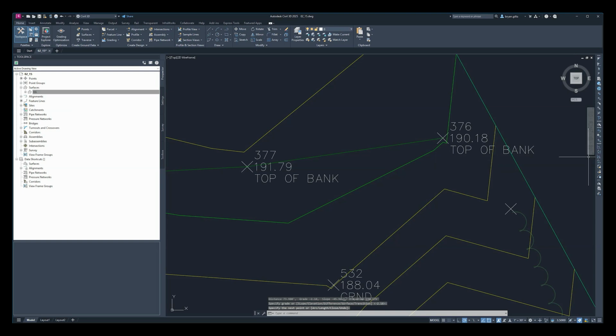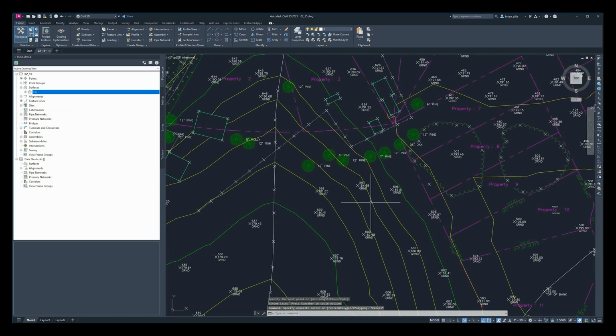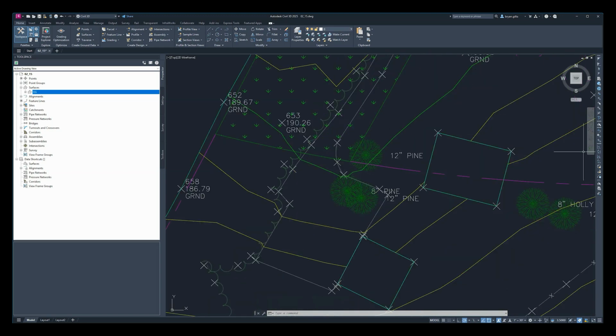So now that we have that feature line created, let's pan to the south lines of parcels named Park 1 and Property 2. So again, if we zoom all the way out, it's going to be that area up here. And this time, instead of using the windows up here, we're going to type in the command PL, capitals, for polyline, press enter, and now we're going to be able to start specifying the points to draw this feature.